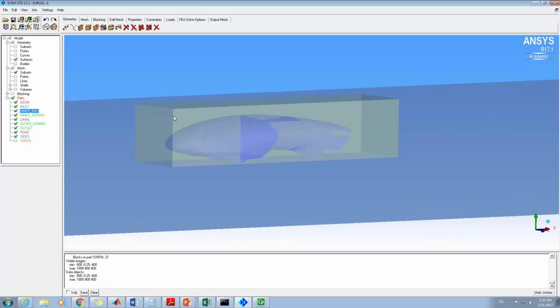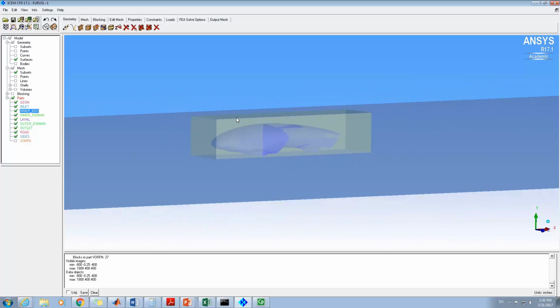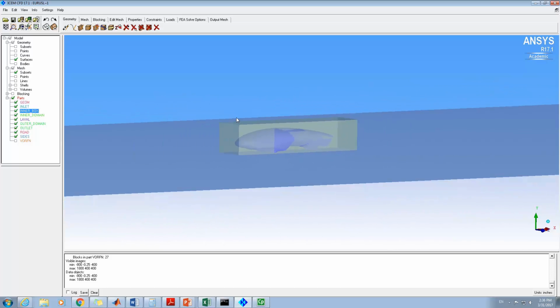Also, of course, you have to move around those mesh points along these 6 surfaces of this inner box so that the unstructured mesh points on those surfaces can match the structured mesh grid points again on these 6 surfaces, just like what we just did, correct?